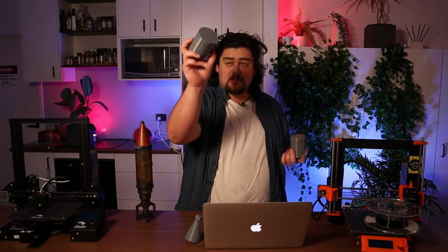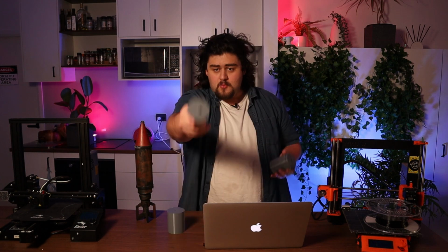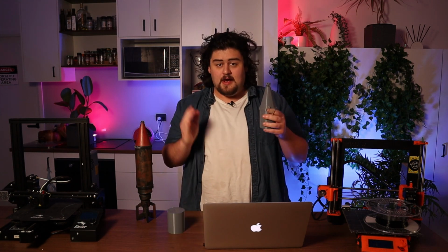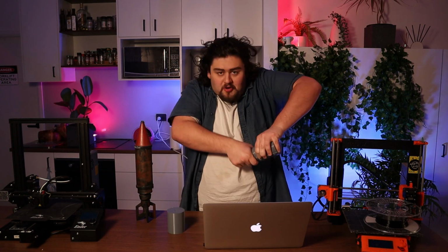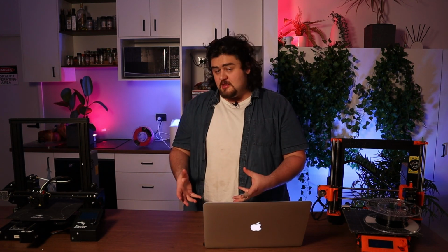If it didn't have these joining pieces like this one, they would be a nightmare to align and glue properly. But with them, it's a piece of cake. And on top of that, it's going to make our part stronger as well. Now we want to use supports as little as possible, so when we're designing the part, we should be taking every opportunity we can to minimize overhangs and bridges.